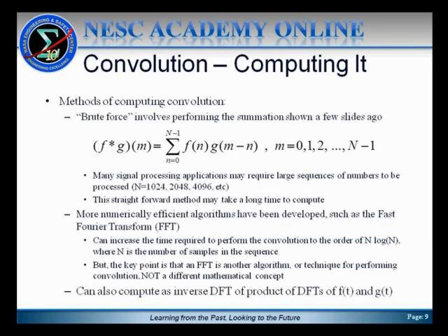PSD is just a technique that includes some additional techniques for refining or conditioning the data that you're going to analyze to make it a little bit more manageable. But again, FFT is not a different concept, it's just a different technique of computing discrete Fourier transforms. And you can also show, as we discussed earlier, you can compute the convolution as the inverse DFT of the discrete Fourier transforms of the two signals being convolved. That also is very efficient to do.